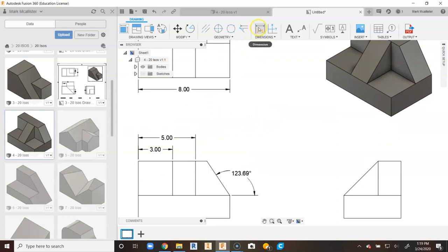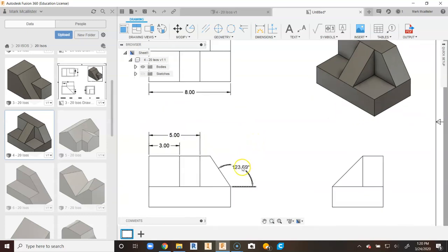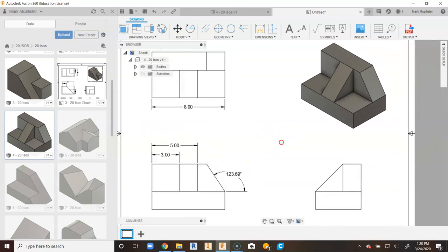Now in the video, we probably went in and did from here to here, and you could put in a 6, and you could say I could honestly just draw a line over 2 from the side and cut a triangle out. But if by chance you ever do a chamfer that's based on a specific angle, this is how you would dimension it. We'll now do our depth dimensions.